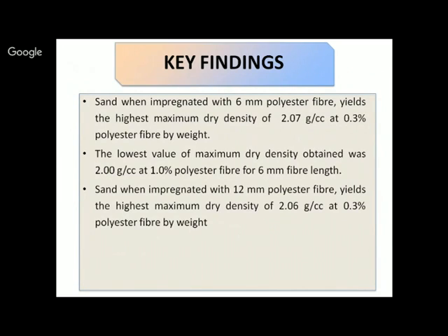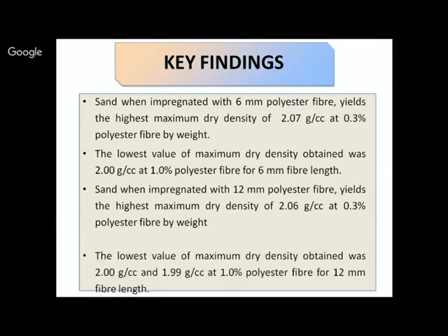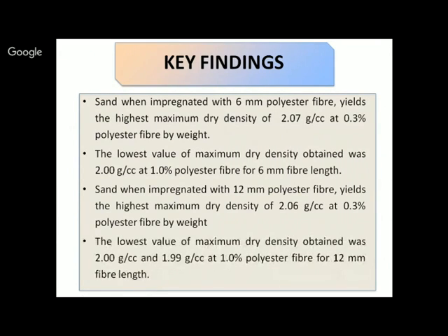The decrease in maximum dry density could be because of the lower specific gravity of fiber, and also due to the balling and curling effect of fiber when the fiber content is excessively high. Fiber intermingles with itself and forms small balls, due to which sand is not able to mix uniformly, and hence some portions of sand and some portions of fiber are distributed non-uniformly.